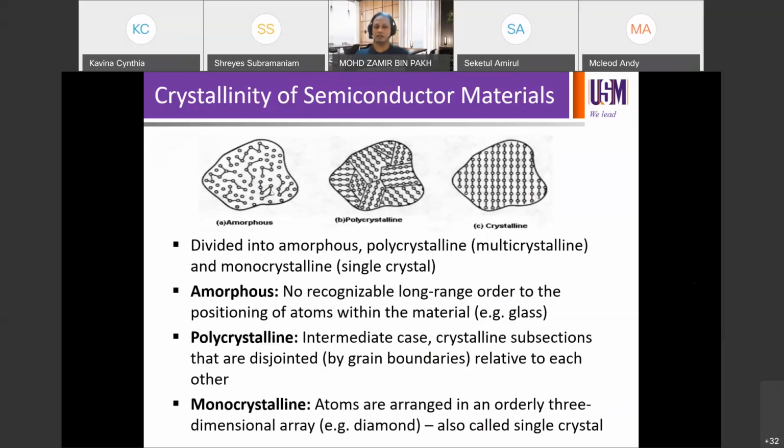So if you look at this crystalline arrangement, the lowest quality is amorphous because they don't have any crystalline arrangement at all, and that will lead to what we call a deleterious implication for the device or the semiconductor materials in terms of the carrier lifetime inside. The carrier cannot survive so long, and the carrier will recombine so fast, it will just be gone from the system, and they cannot conduct electricity anymore. Okay, we'll see later on, don't worry yet.